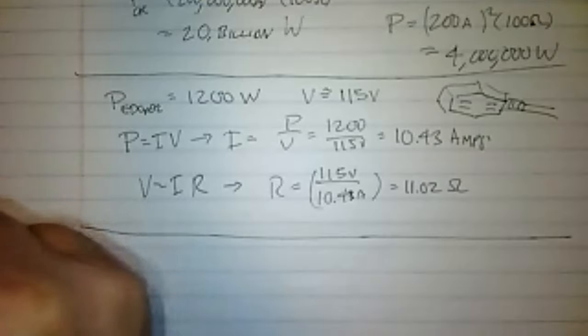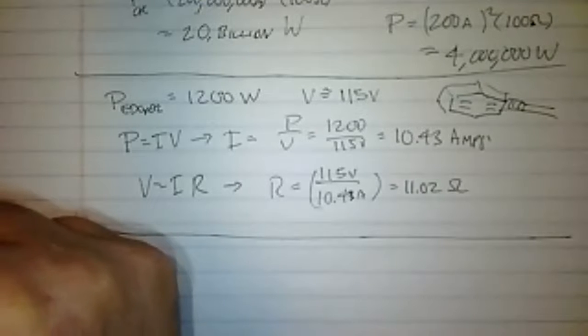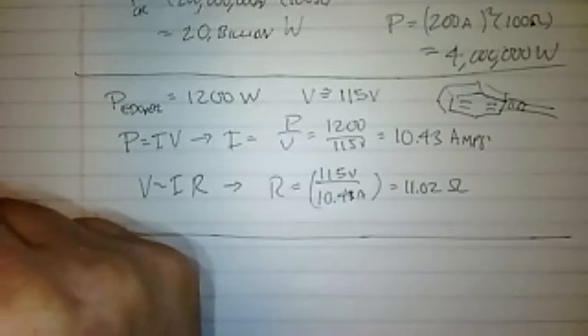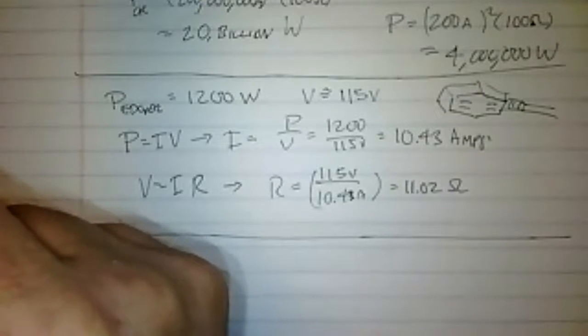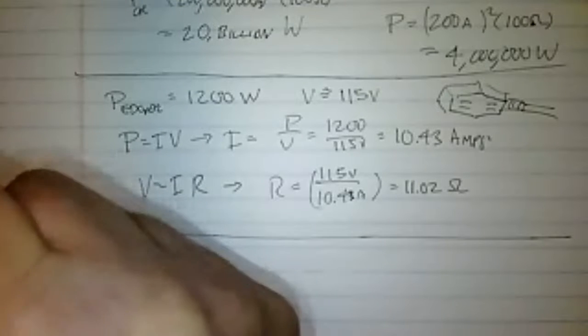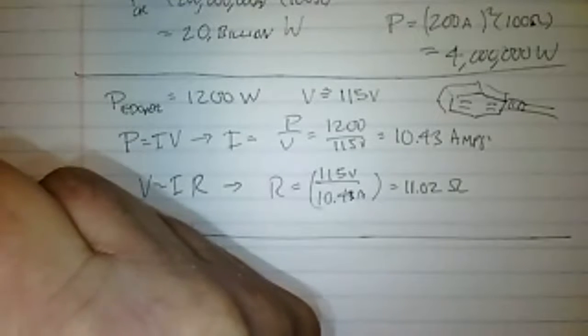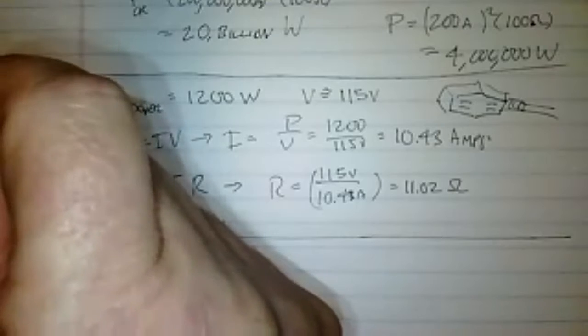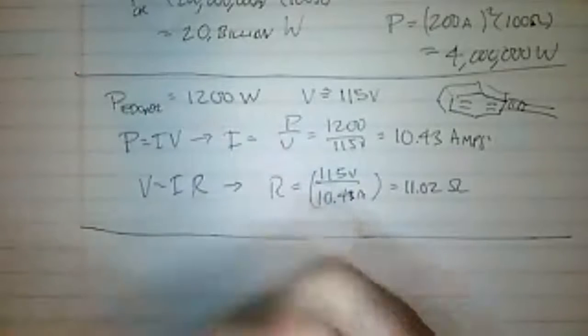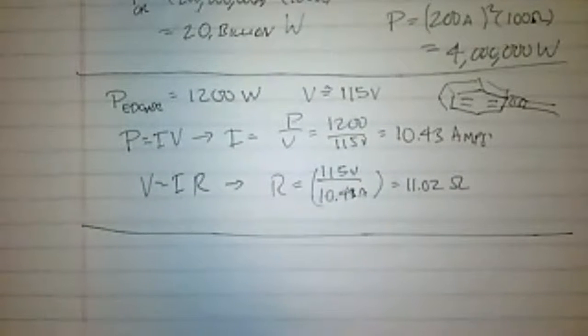That generates electricity to keep the battery charged. You don't run everything directly off the battery; the alternator is charging the battery and running everything in your car. So when your alternator goes bad, you will see your headlights starting to dim, and you might think your battery's dead, but it's more likely your alternator that's having the problem. So that's another thing you can use.